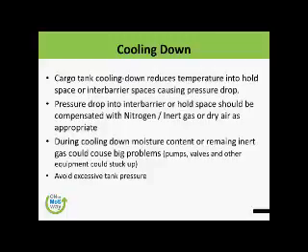When you are doing the cooling down, you will have to watch your cooling process, and as it is contracting, your tank annular space pressure or interbarrier space pressure will drop and you will have to give further nitrogen to it.